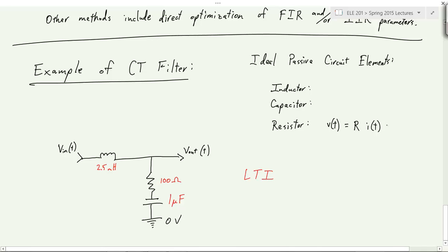For a capacitor, and so this is drawn like that. For a capacitor, you have a proportionality between the derivative of the voltage and the current. And of course, there's another constant here. We'll call that C. It goes there. That tells you the proportionality here. That's the capacitance. And of course, this is drawn like this. And finally, for the inductor, now you have a relationship between the voltage and the derivative of the current. Derivative on the other side. And we have L here as the inductance.